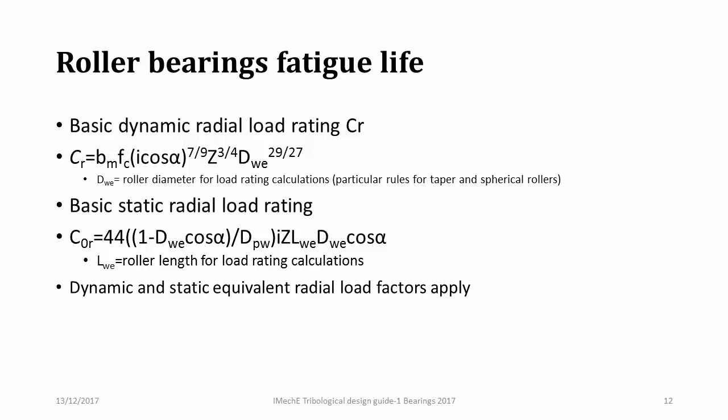We always profile the end of the roller contact zone in order to avoid edge loading stress raisers. So the effective roller length is something that bearing manufacturers have to know, and if you really want to know what it is, you may have to talk to them. And then there are dynamic and static equivalent load factors to apply, just like for a ball bearing.